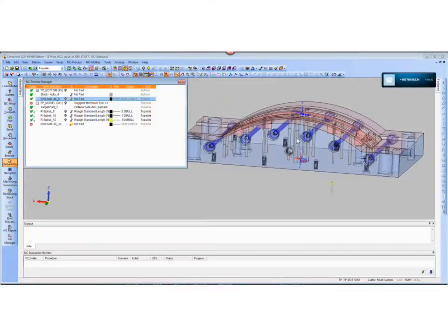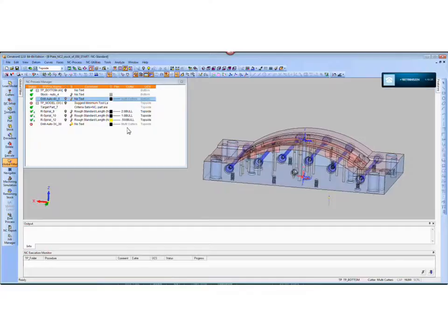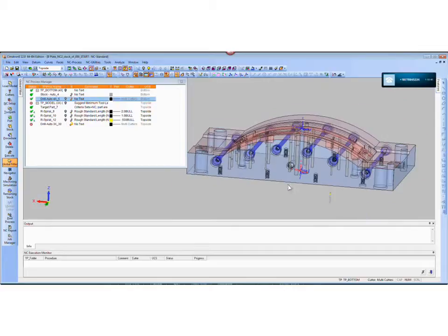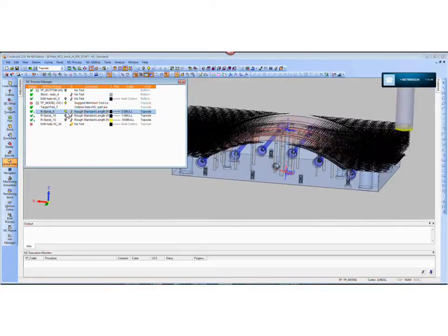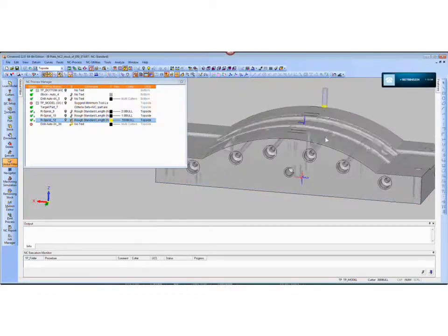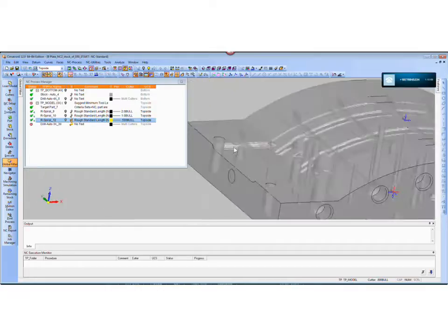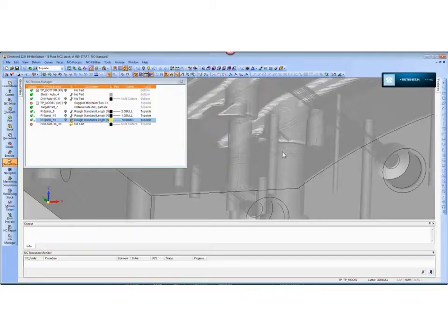And I actually did do roughing. I want to explain that I went ahead and roughed some steel out, did some more roughing, and a little more roughing. And at this point, I can show you what the remaining stock looks like. So I've got this milled down to say within 50 thousandths or 100 thousandths or whatever you want to make it.